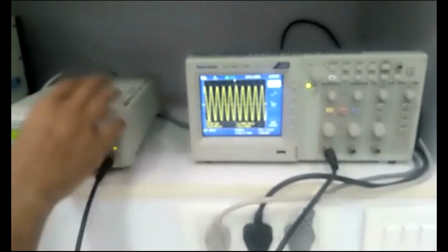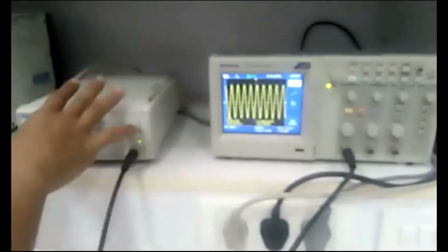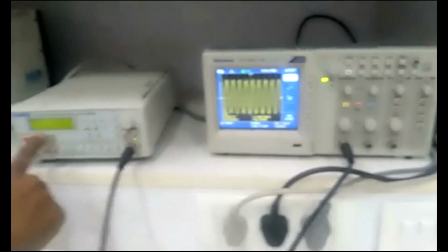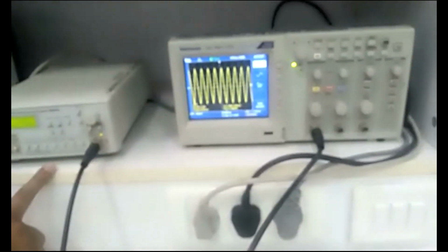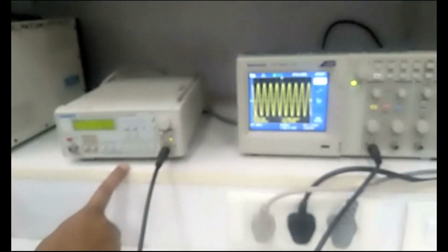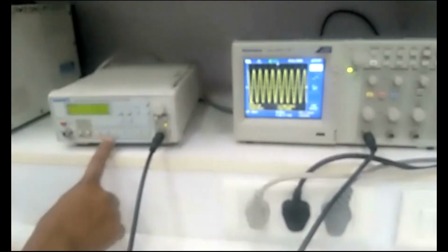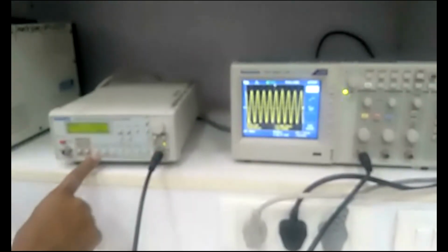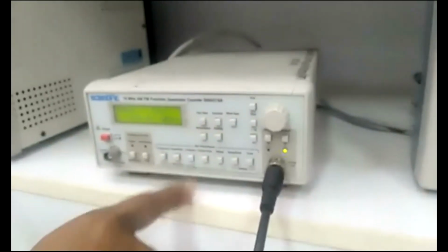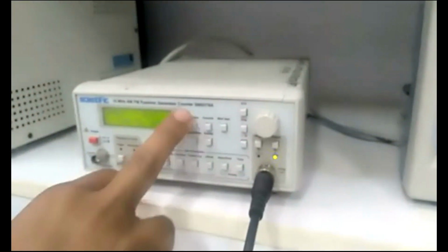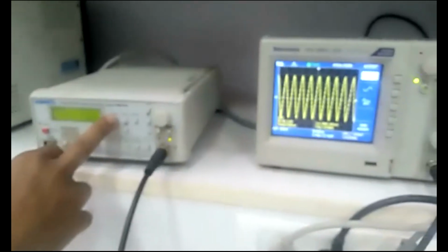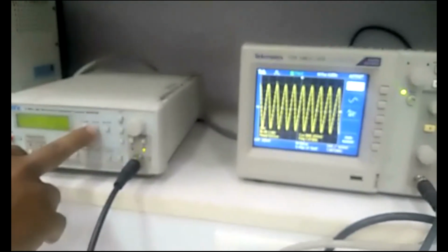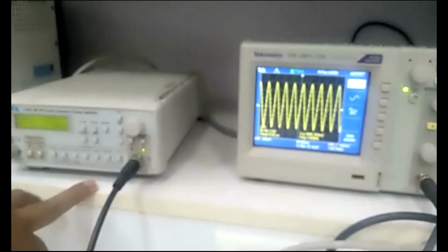Directly from the function generator, right now we are generating a sine wave with an amplitude of 100 millivolt and a frequency of 19 hertz. You can change the amplitude, frequency, and also the type of the wave from here. As you can observe, there is a set parameters option that we are going to use in order to modify the particular function. If we change the function, then we can have a different function.